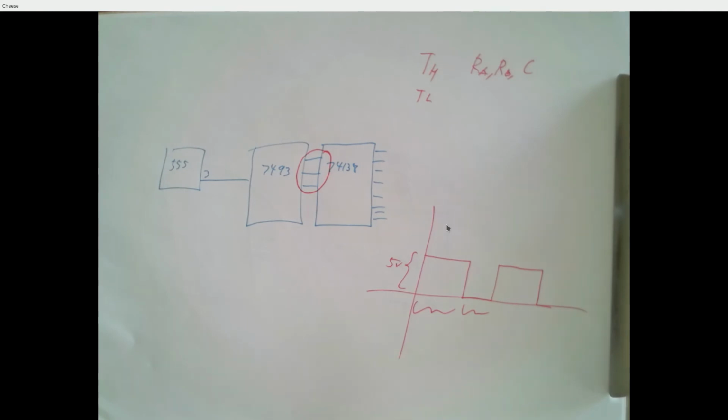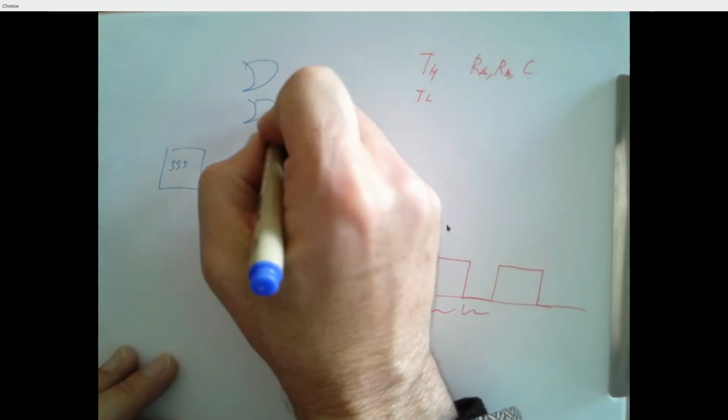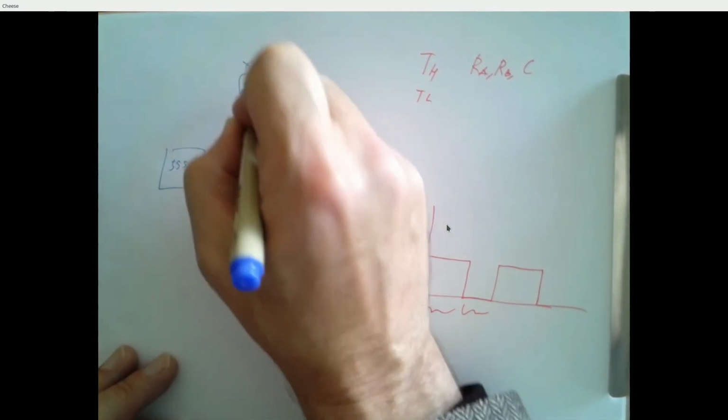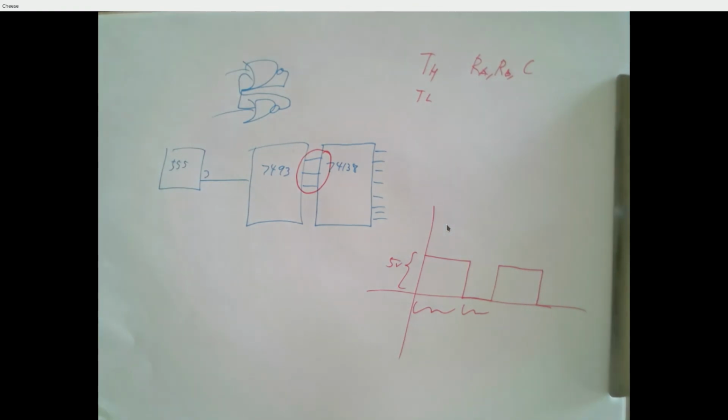And once we understand what a D latch is, we're going to take a pair of D latches, add some more circuitry, and create something called a D flip-flop. And if we have a D flip-flop, we're going to take some of those and put them together into other things and create a T flip-flop and a JK flip-flop. And at any point, we could go back and draw this in terms of a billion, maybe not quite a billion, but a billion of these cross-coupled NOR gates, right? But if we have to go back to that level every time, it's going to make life really confusing.